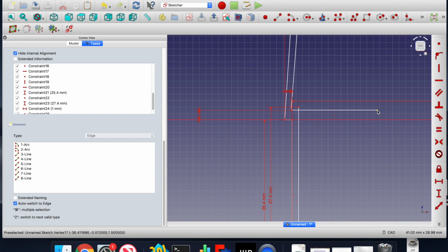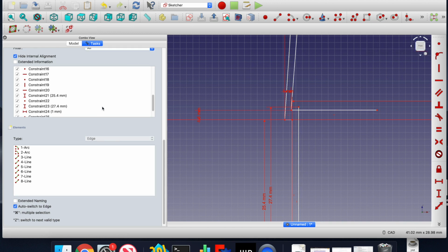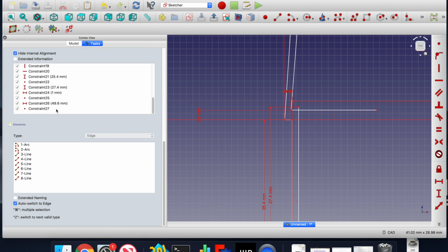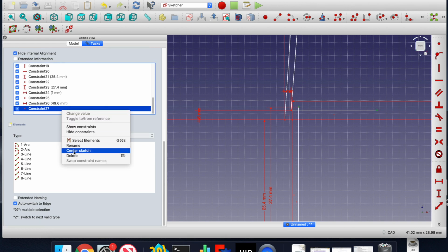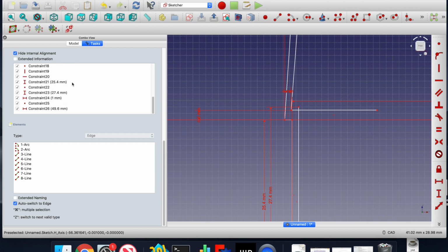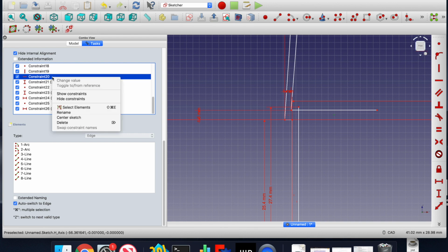So I probably need to line these guys up too, so let's just do that. Oh, I didn't like it. So again, I'm over-constraining the sketch. Not sure why. So it's a matter of going through and figuring out what I did wrong. Some of these I remember, so I know they're not the culprit. Saying the line's parallel. Okay, so get rid of that one.